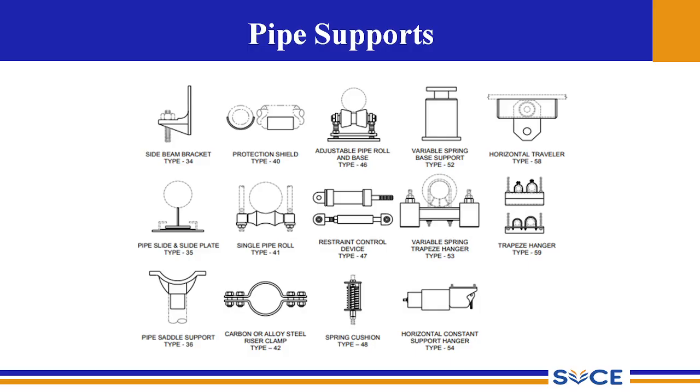So this is a device with a curved base for cradling the horizontal pipe, and it slips into a nominal diameter pipe stanchion. So it is similar to that of vessel supports, where you install saddles at both ends to support the loads. In the case of very large diameter pipelines, the pipe saddle supports are normally used so that the load is distributed properly.